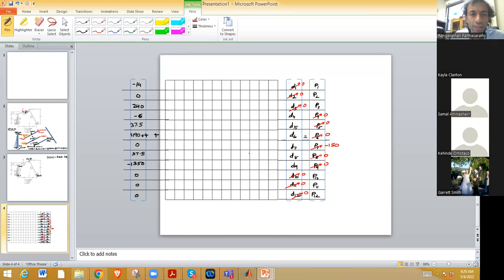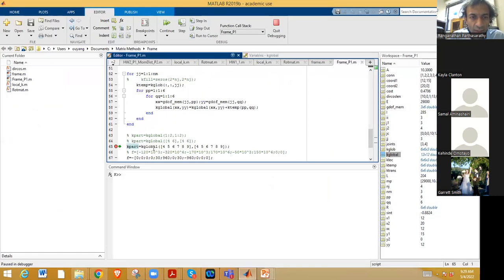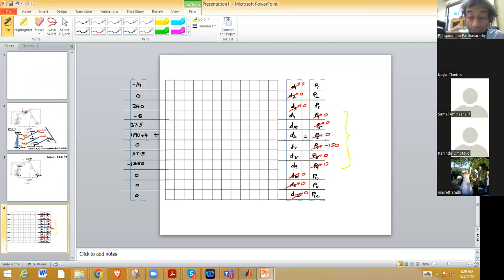Okay, we have all of these. Now, what is our partition? How should we partition our matrix? The known loads are all of these from 4 to 9. Actually the partition is what I showed you in the previous one. It is the same, 4 to 9. The rest are 0, right? So you just partition from 4 to 9. Then you have your fixed end moments and all the fixed end forces. So let's enter all of these now.